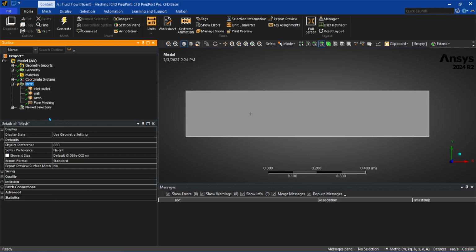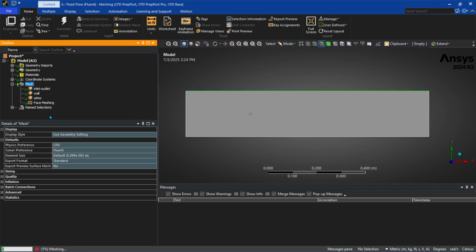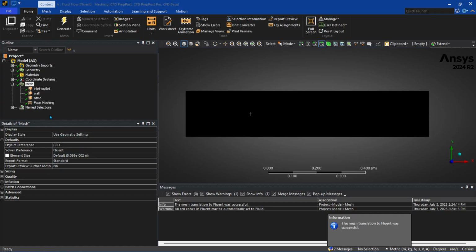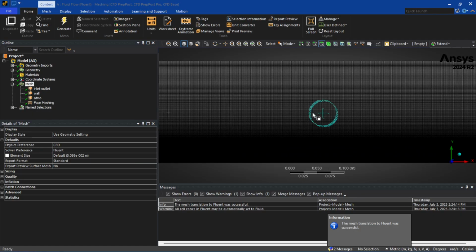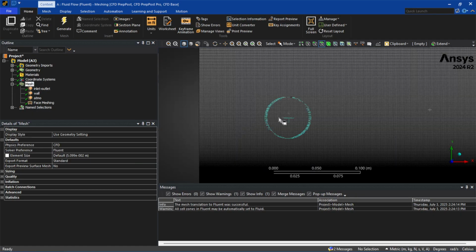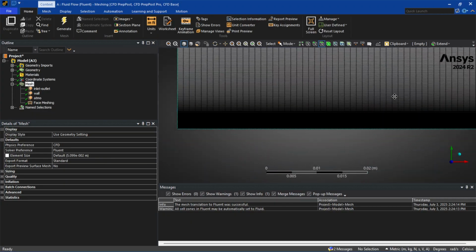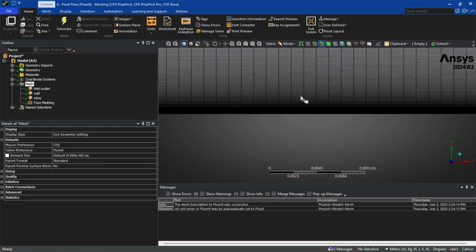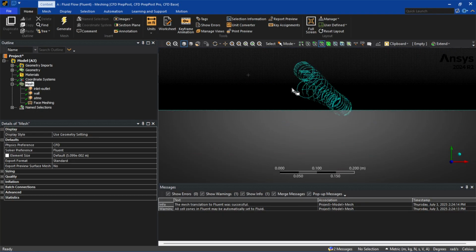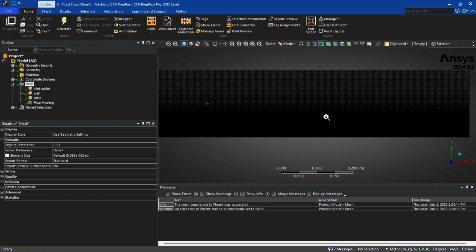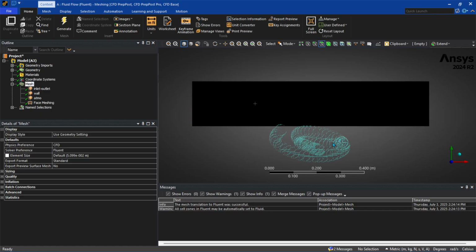Now we mesh, and yeah, we're gonna have to give it some time, or not. That was surprisingly very quick, very nice. But yeah, you can see what the bias factor does. The top here are more coarser, and then as you get closer to the wall, they get very, very small. This is what we want, because we want most of our focus down here. So, and also pardon this mouse glitch I have. This is caused by the GPU, so just don't mind it.